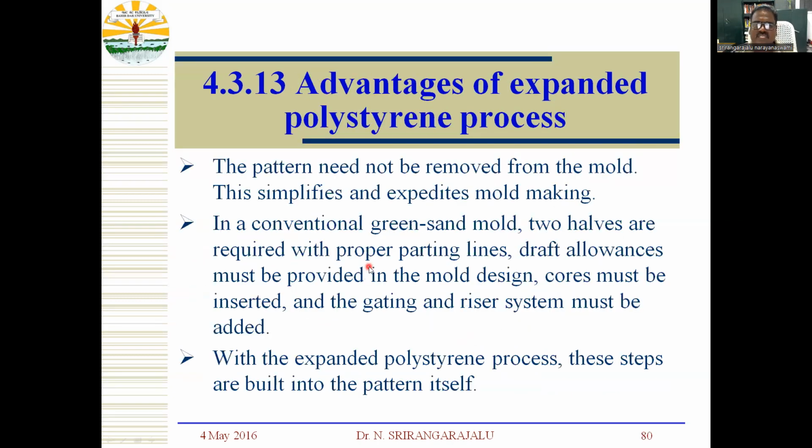The advantages of the expandable polystyrene process: the pattern need not be removed from the mold. This simplifies and expedites mold making. In a conventional green sand mold, two holes are required with proper parting lines. Draft allowances must be provided in the mold design. Cores must be inserted, and the gating and riser system must be added. With the expanded polystyrene process, these steps are built into the pattern itself.